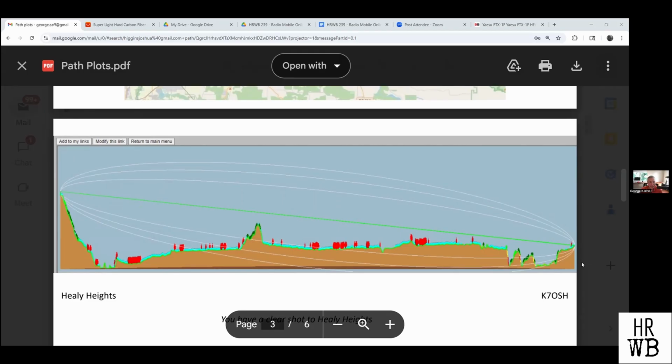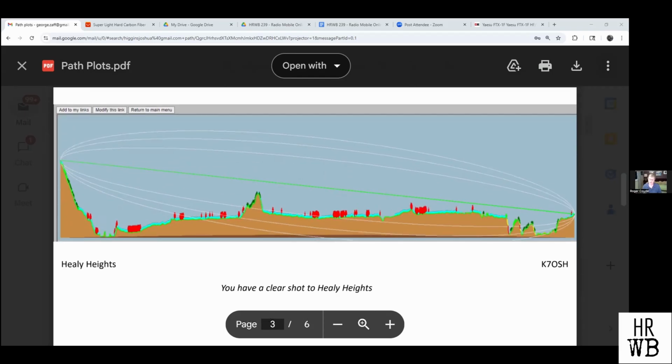But in fact, this is not part of the Longley-Rice. Longley-Rice doesn't take into account the line of sight. This is a part of the program that I implemented myself based on the 2-ray method. So the program has 3 zones. There is line of sight, you have beyond line of sight, which is Longley-Rice. And within line of sight, there is a zone where you have ground reflection and direct path. And in between the Longley-Rice zone and the 2-ray zone, there is a progressive mix